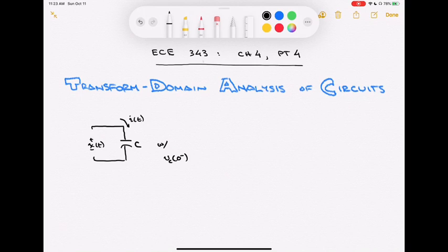If we take that circuit and Laplace transform it, because I've drawn this with an initial condition, we know that the unilateral Laplace transform is the appropriate one. We're going to transform every element on that circuit picture and come up with a transform domain equivalent. I'll draw it out, and then we will verify that this is the correct representation. I'll write over here the transform of the input, which we'll call X of s.